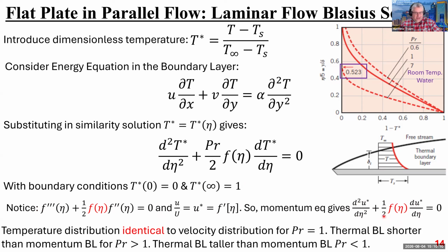One point of confusion, and I actually had to look this up because I'm like, well, look, if u star is f prime, right? Why is this f not like the integral of f, right? Why don't you bump this up by like an integration here? And I had to look this up because that seemed reasonable to me. So it turns out the reason we don't do it is because we already know the solution to the Blasius equation, right? You already know that, and so there's actually no mathematical benefit to bumping this up if you just leave it as this known function of eta, right?